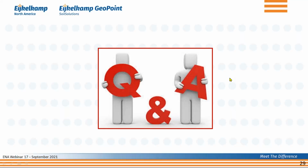You can use the CPT tip resistance and the friction ratio to figure out an estimate of the shear wave velocity. But it's not as accurate as measuring it directly. So CPT and the seismic cone really is an enhancement. They complement each other, so it makes a lot of sense to use them together.